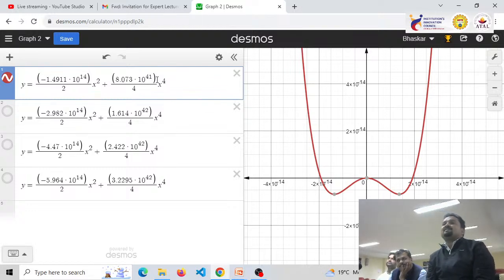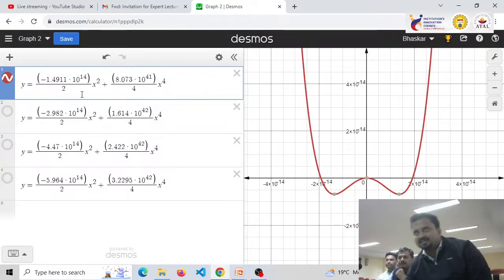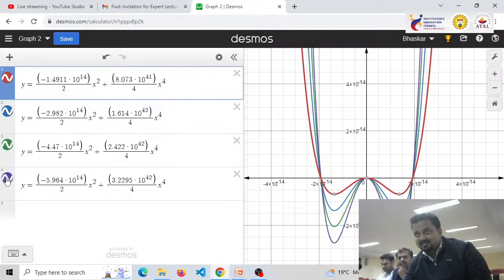Now, the same thing that I have done for TFE equals 30 nanometer, I need to do for 60, 90 and 120. So let me just enable these. Again you can see the radius of curvature for each one of 30 nanometer, 60 nanometer, 90 nanometer and 120 nanometer is negative. So that confirms the presence of negative capacitance. In my previous graph, I showed you charge versus voltage. There also we confirmed the presence of negative capacitance, and here also we confirmed it.